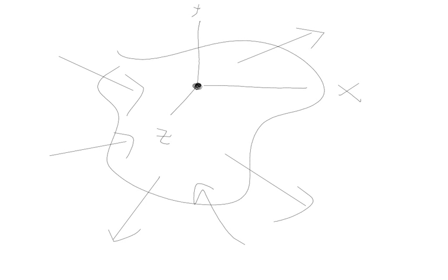Okay? So let's take a step back here and look at our definitions. We know that as far as stresses go, we've got normal stresses and shear stresses. A normal stress always acts perpendicular to a surface, and a shear stress always acts in the plane of a surface. Now, the other thing that we want to make use of is our standard Cartesian coordinate system. It's a very nice, simple system because you have three axes that are all mutually perpendicular, which makes things easy. When your axes are 90 degrees apart, then you can make use of trigonometry.